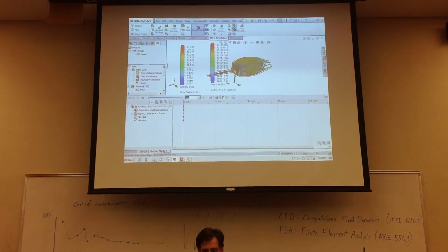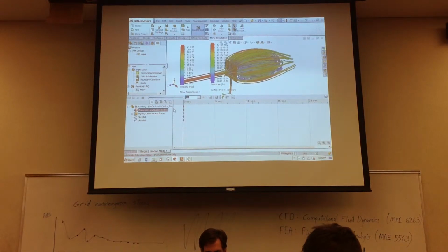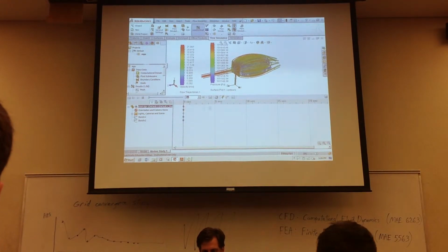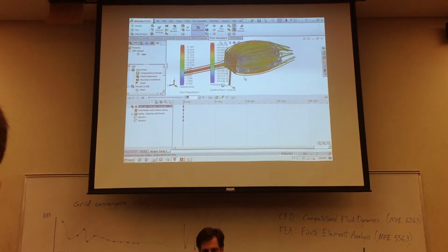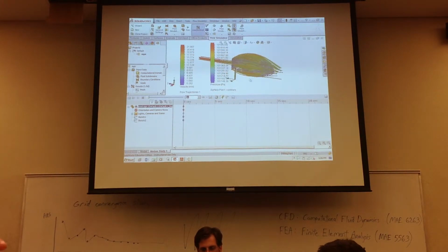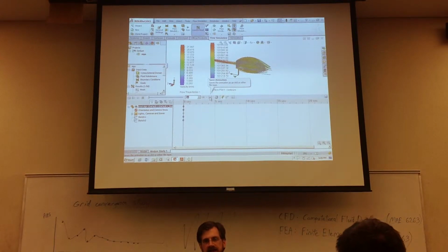Oh, it's not giving me these options because there's no assembly here, but this by default is just going to do solid body animation, but all you do is establish the keyframes down here on your timeline from 0 to 2 seconds. So maybe this is one keyframe, and then maybe you rotate into this orientation and establish a keyframe at 2 seconds, and zoom out, zoom in, establish a keyframe there, and just save it as an animation. So if you have questions about that, come up at the end of class and I'll be happy to show you in more detail about the animation.